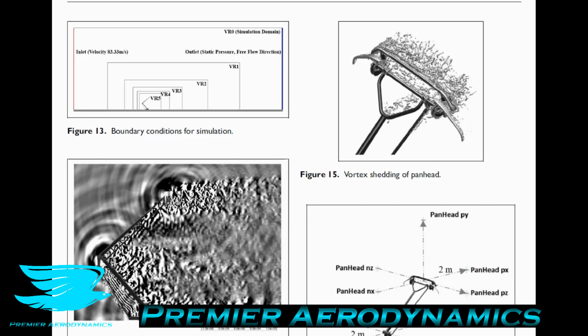So what they're saying here is the frequency range of the analysis was 3,000 hertz. They're considering all noise up to 3,000 hertz. So to consider these frequencies, they need to be sampling at least 6,000 hertz, and this will stop the aliasing effect. Now, with the aliasing effect with this particular case, I think you need to know in advance what the highest tonal noise will be to be able to make that call definitively. However, if you know any more about this, let me know in the comments below.